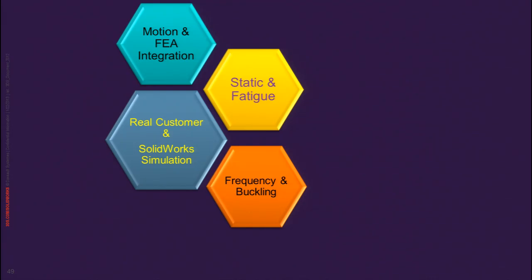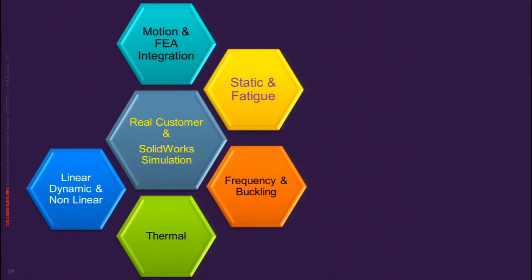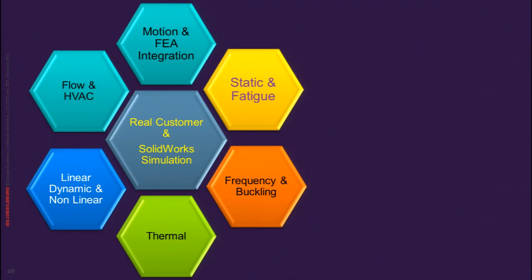Frequency, the first step for dynamics, and buckling for those cases that are slender and under compression. Thermal for the LEDs company. Linear dynamic and nonlinear for many cases. And finally, flow and HVAC for those cases of ventilation and air conditioning.